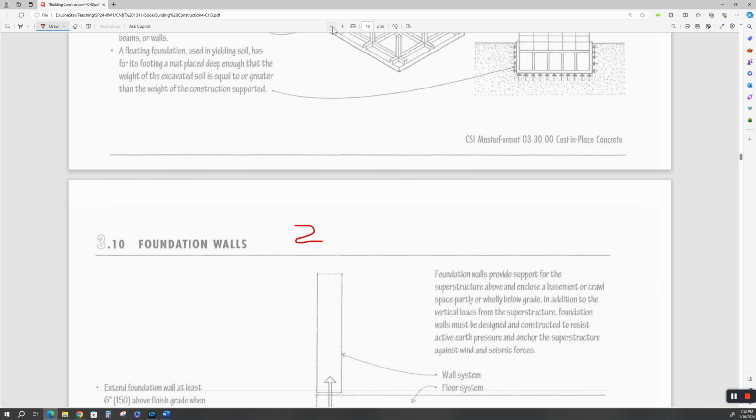All right. This is a concrete ground slab. It's a slab on grade. If this really was a basement or a sub level, which it obviously is, because here's the top of the soil, and this is underground, then what's going to happen? You've got the propensity for water, since you have a drain here, to migrate up through this slab and leak inside your basement or substructure area, and that's bad.